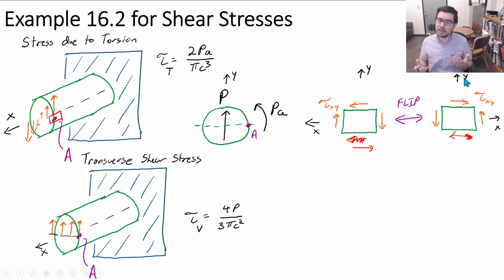This is maybe a little bit confusing, all right? And to be honest, shear stresses, how do we put it? Direction doesn't matter so much as when we have compression and tension, but it does matter when we have to add and superpose them on top of each other. We need to make sure we know, are we adding two shear stresses acting in the same direction, or is one acting in one direction and the other acting in the opposite direction? So it can be a little bit confusing, and it is important to be able to keep track of this. And even, as you see, I made a boo-boo here.